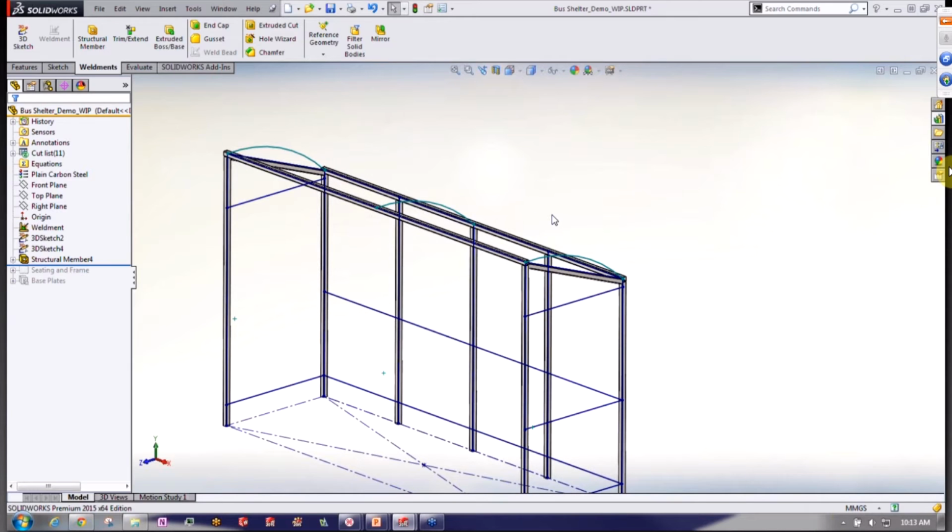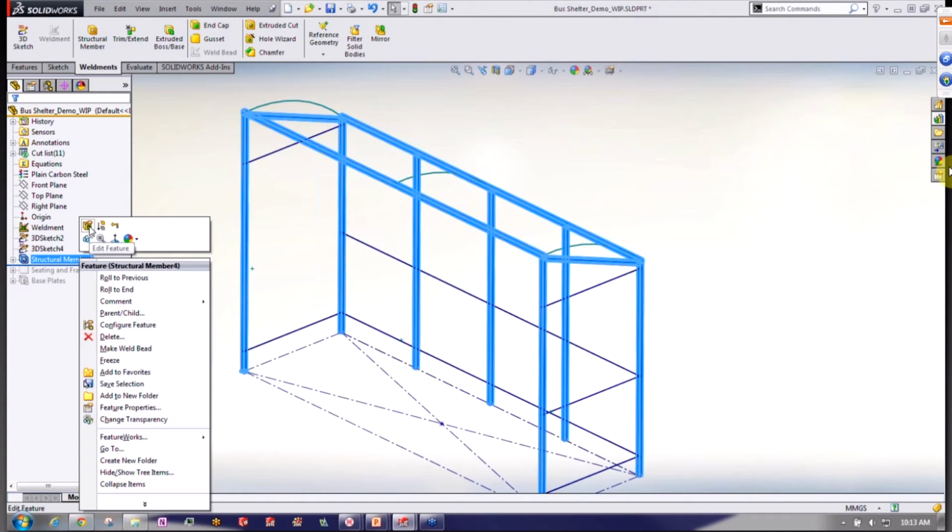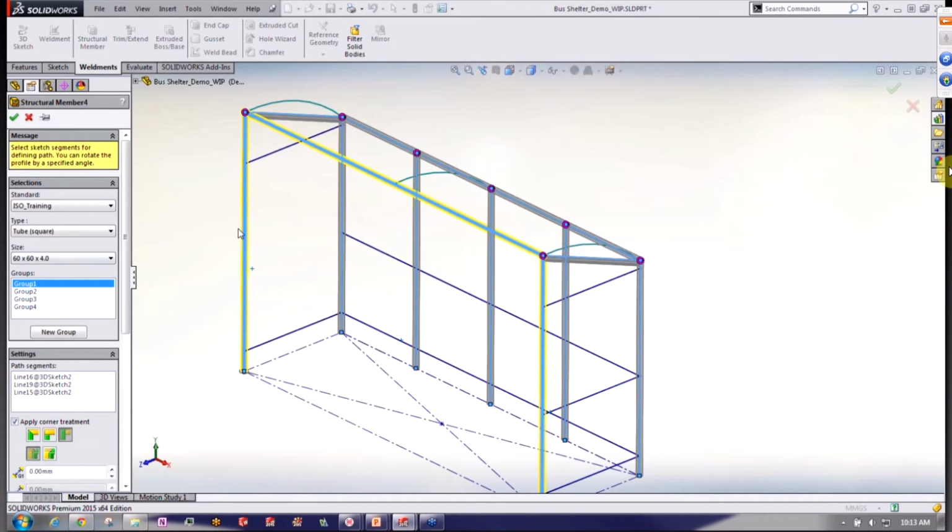So we have a question, why would you want to choose new groups instead of just selecting all the lines? You're actually forced to break down the selections into different groups. SOLIDWORKS likes us to select things either end to end, like I did these first groups here, or they need to be parallel. And really a lot of that has to do with the trimming.